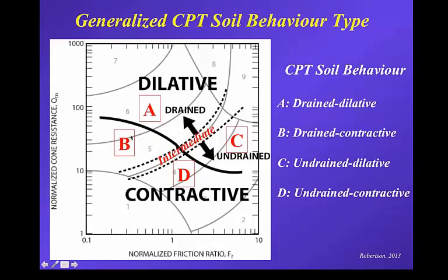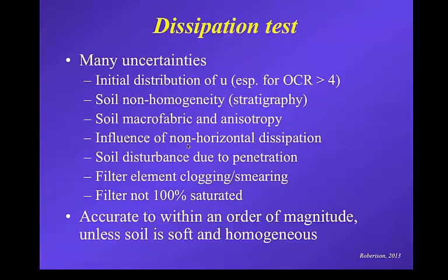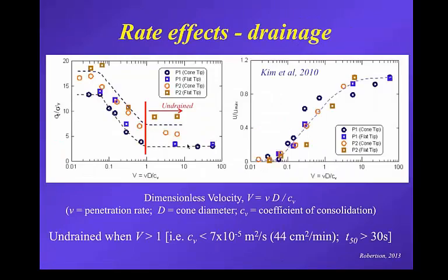Well, that's slightly off topic, but it sort of does. It's captured in a way in this chart, where most of the liquefaction screening for sands is up in region A and B. Most of the data for case histories of liquefaction is in sands in region A and B, and it's only in the very silty sands that begin to get into this region of partial drainage. But if you come back to here, which way am I going? Yes, the rate effects.